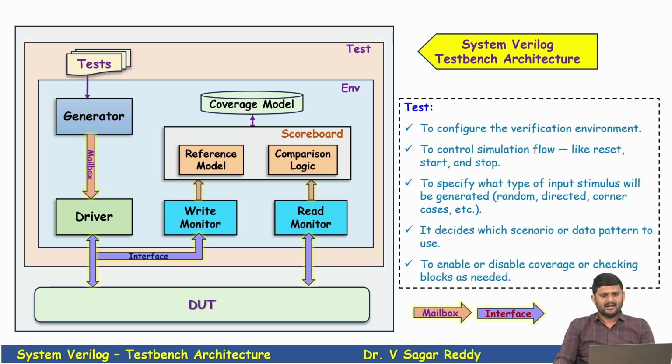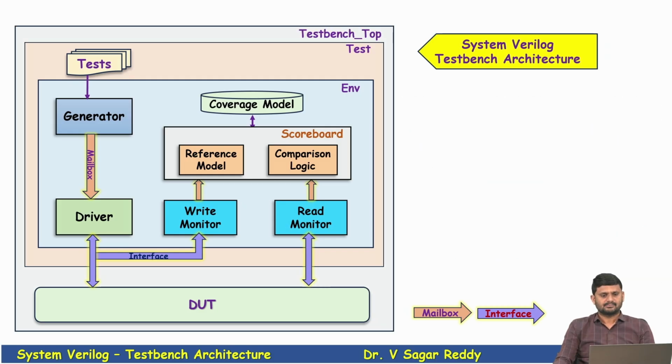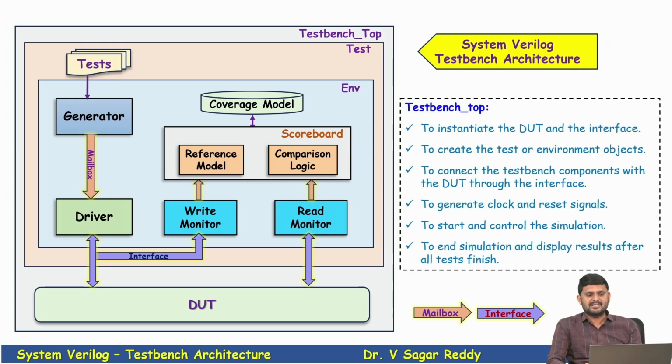So now if we see the testbench top. Finally, this is the complete picture of the testbench architecture, known as the testbench top. The testbench top is the outermost module. This is the entry point of the entire simulation. It is a module, not a class. It has six critical responsibilities.